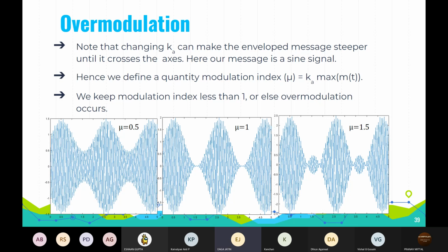So in the sense of definition, it is almost always considered a fault condition, or in layman terms, we can say the signal is going off the scale. Over modulation results in superfluous emission of the modulated carrier and distortion of the recovered modulation signal. This means the envelope of the output waveform is distorted.